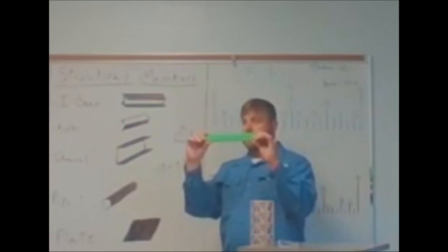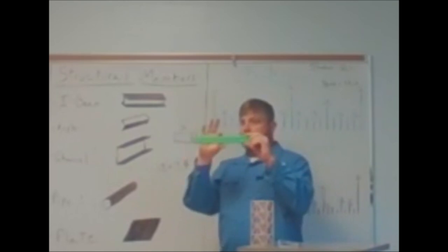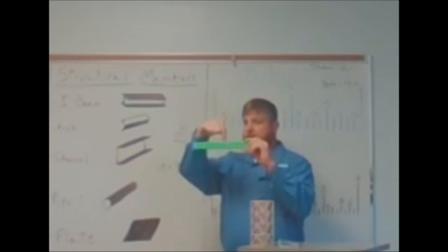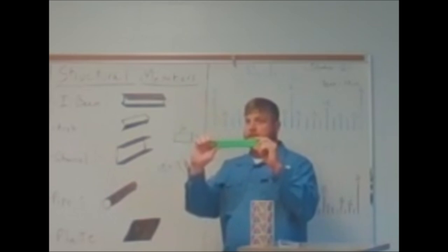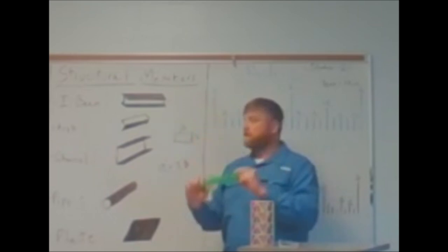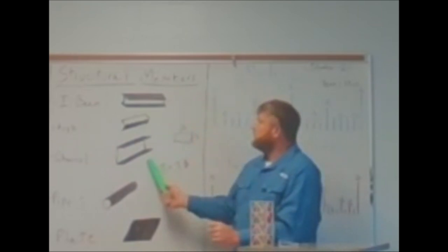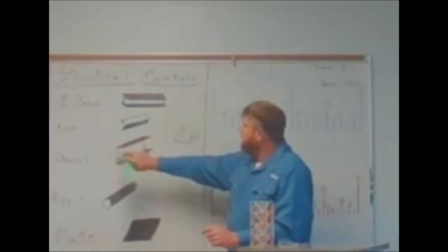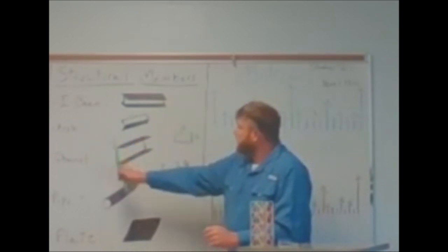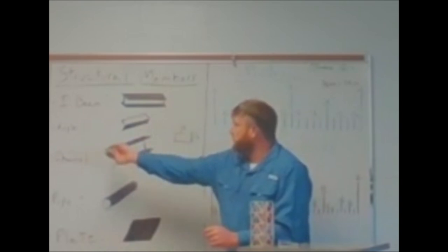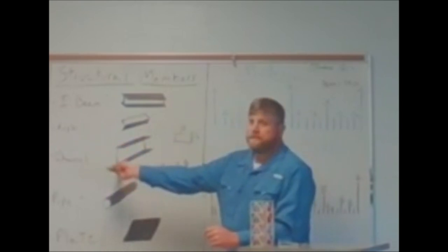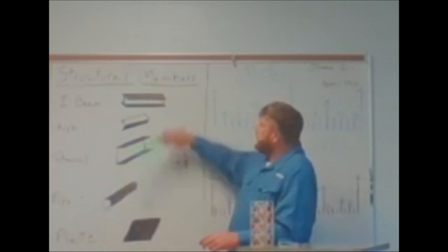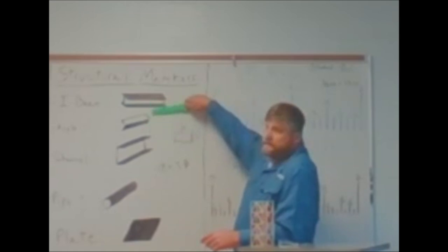But if you turn it in this direction, where it's extruded and the force is being applied here, there's a lot of structural integrity. Yes, channel would counter more forces than angle would because you have here, here, times two, and here, instead of just here and here.